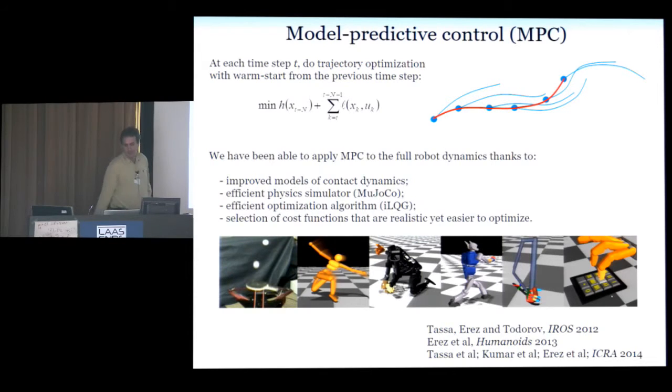So this is a very popular methodology. Actually, it's one of the oldest tricks in the control book, really. It's routinely applied to things like chemical plants because their dynamics are slow and smooth enough so that your optimizer can outrun the real-time clock. So obviously the catch is, can you optimize faster than the real world is moving forward? If you can, then you're in business. If you cannot, then forget it.